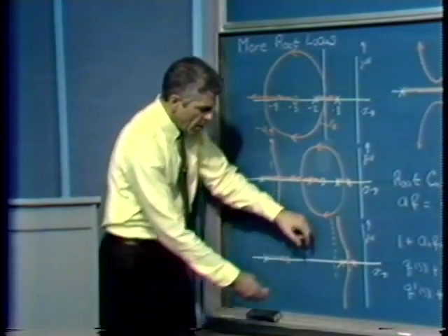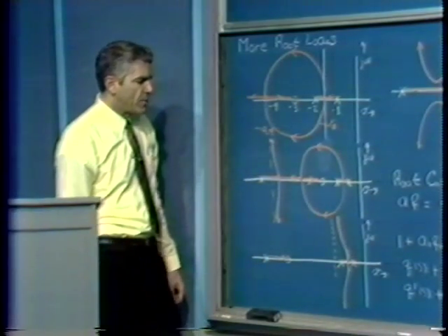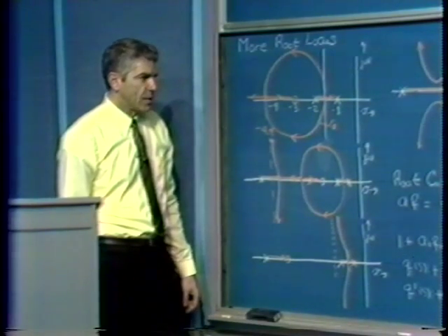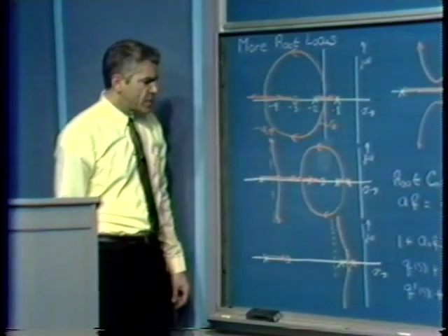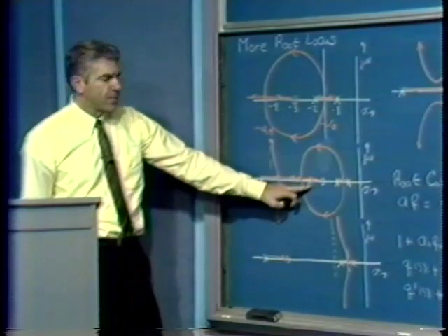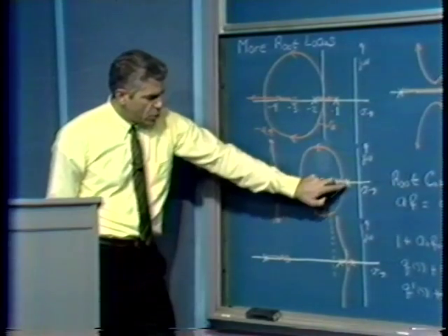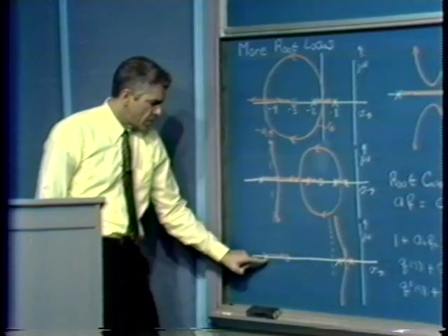Similarly here, because these branches move back, if we do an exact calculation, we find out that we can get greater desensitivity without paying a penalty of relative lack of stability. It's interesting to look at the dividing line between these two apparently very different forms of behavior. We start out with two poles, a zero, and then a third pole in both cases.